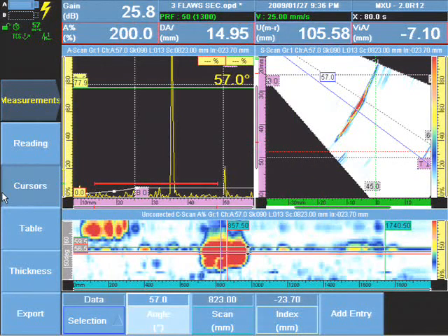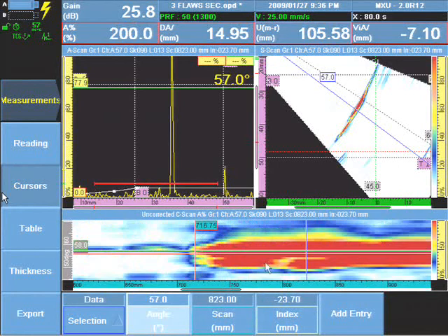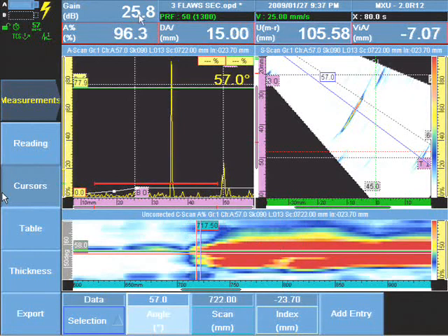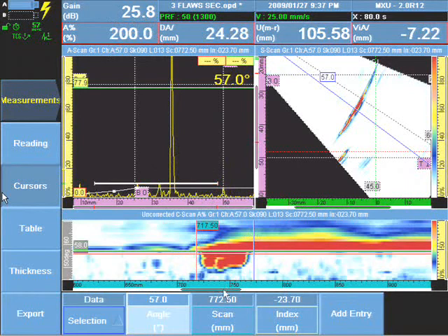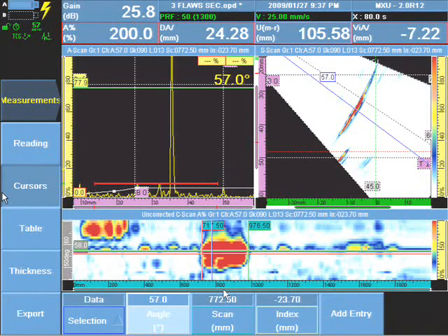The length of the flaw is recorded on the C-scan either by doing a 3 or 6 dB drop on the color palette, or using the data cursor and the amplitude reading to take a digital number for our 6, 3 dB drop, or whatever the code in the procedure requires.